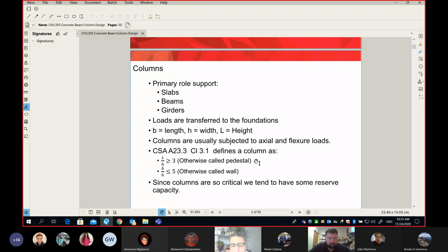What they do is, sequentially, they take the load from every floor and transfer it into the column below, until the very bottom column, which takes the load and delivers it into the footing, and then finally the footing takes the load and spreads it into the soil. Okay, so that's a safe delivery. In general, the load will go from the slab to the beam, from the beam to the column, from the column to the column below, all the way until the load is delivered to the footing system or the foundation system, and then finally delivered safely to the soil.